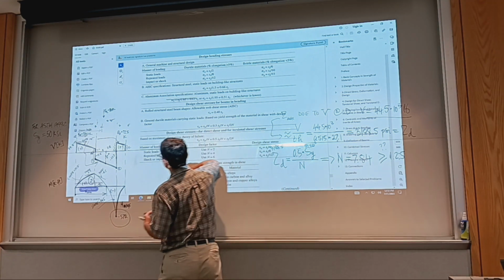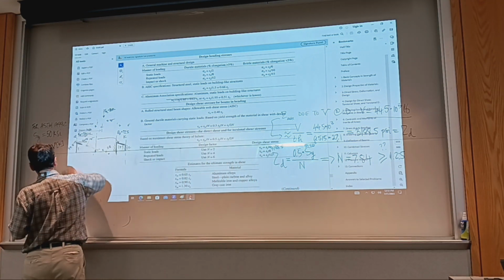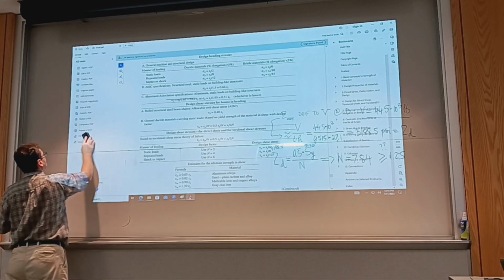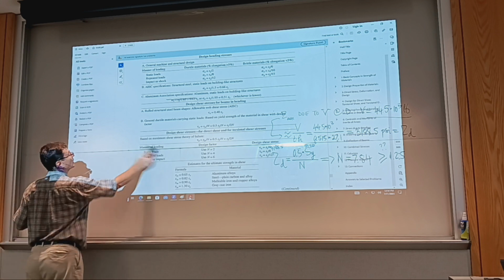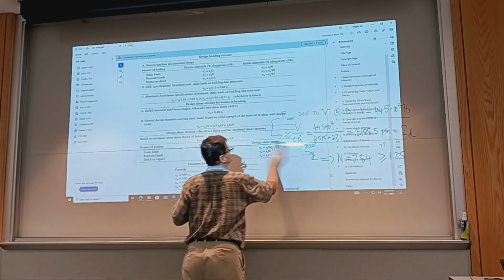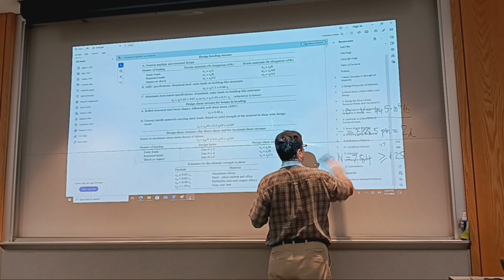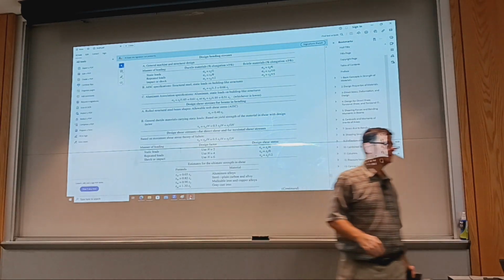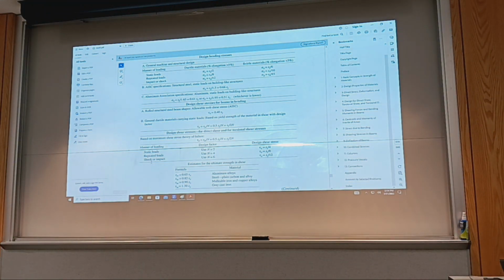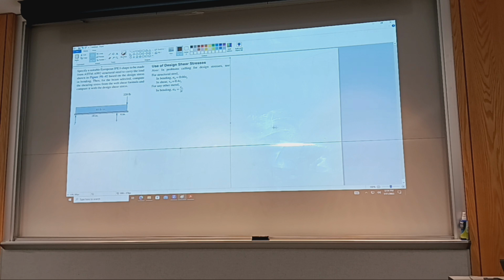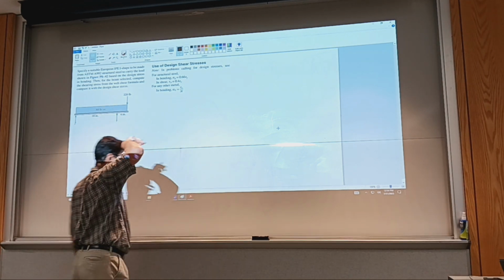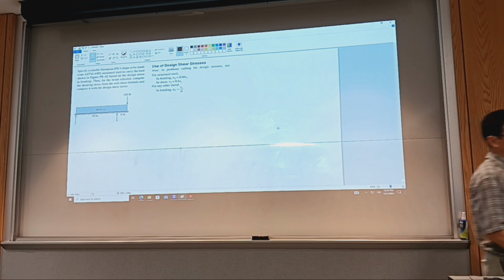Okay. Let's go to the second problem of this type, but it's for a metric I-beam and also for a material that is specified, and we need to draw or evaluate the loads, draw the shear force and bending moment diagrams, select the section, an I-beam, and then verify where maximum shear due to bending occurs.